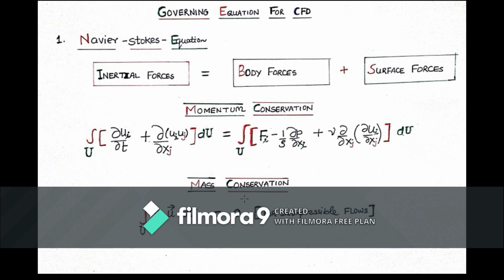The moment I say momentum conservation, we have to look into Newton's second law, which says the rate of change of momentum is equal to the vector sum of all the forces acting on a body. Now we have to understand what kind of forces are acting on a fluid particle. It's either body forces or surface forces.